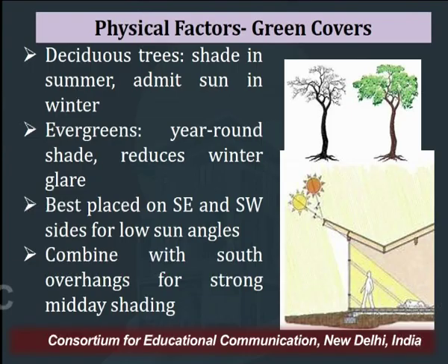So, the best placed locations for the trees and the green cover are the southeast and southwest for the low sun angles, and this can be combined with the overhangs present in the south for the strong overall midday shading.